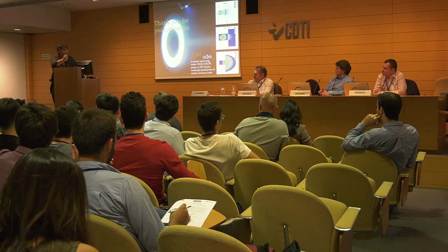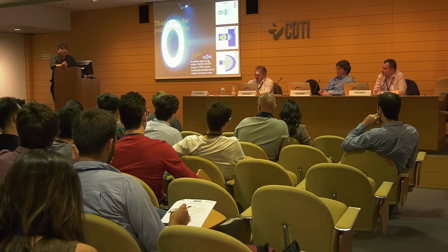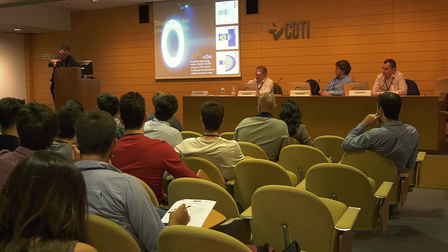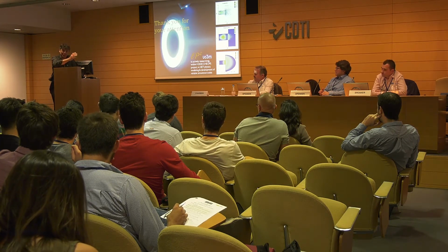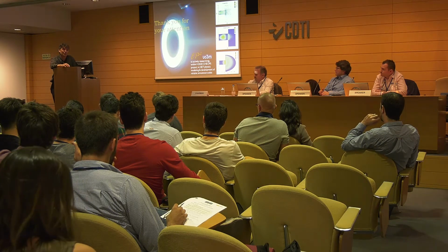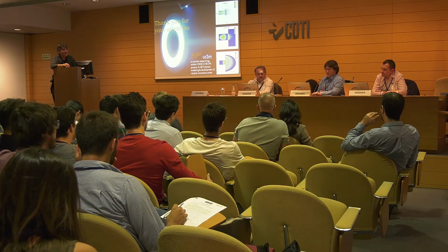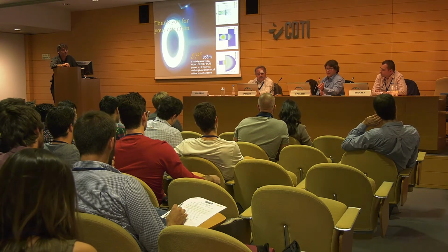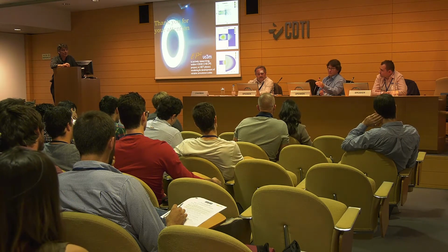Another interesting point, because you commented about the economics, is the issue of the PPU. In the end, the thruster is the cheapest part of the whole system. The PPU costs double the whole thruster, and I think three times as much for the ion thruster PPUs. So from the market point of view, improvements in PPU prices are going to be critical. This is why we mentioned this German thruster, the HEMP, which maybe is not as good as the others from the performance point of view, but the electronics can be half the price. And of course, this is putting it into business.